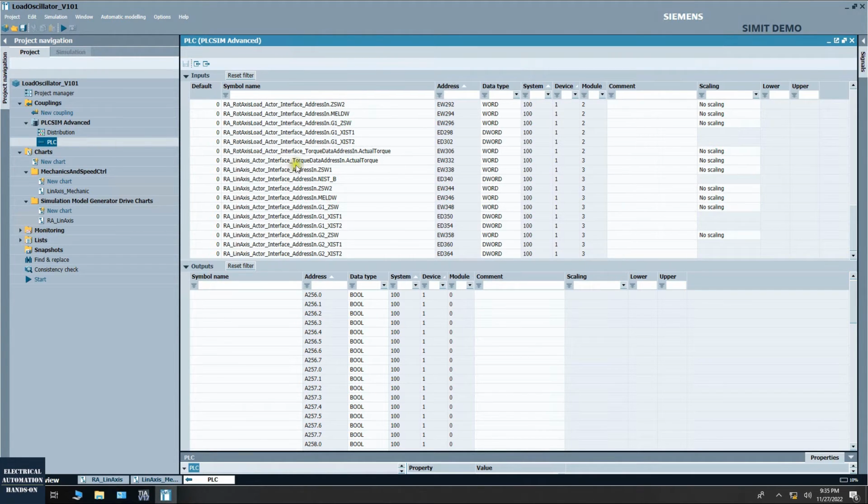Because in some cases, once your TIA Portal got recompiled or got some changes, this interface will have some errors when you do the simulation. Especially this coupling area, which is used to connect the PLCSim Advanced software. So we had better delete it here.